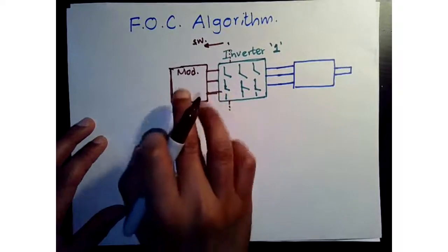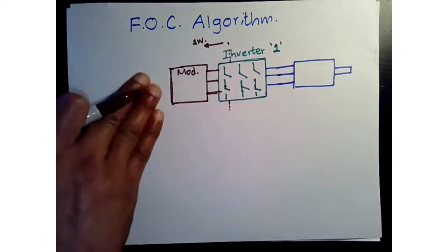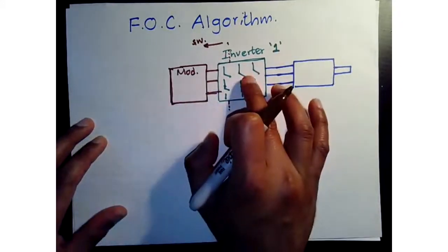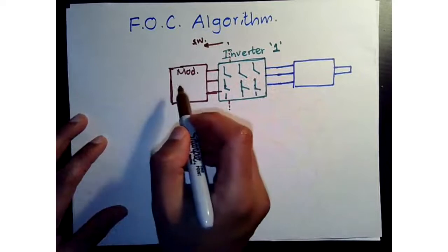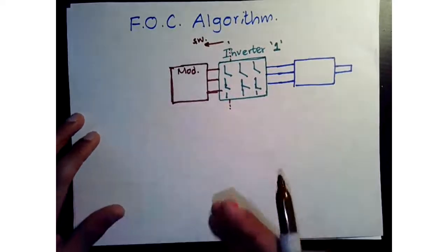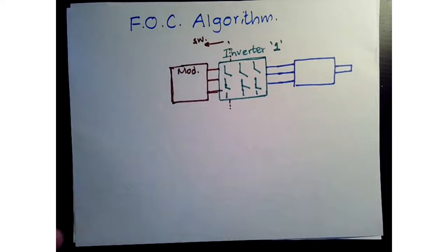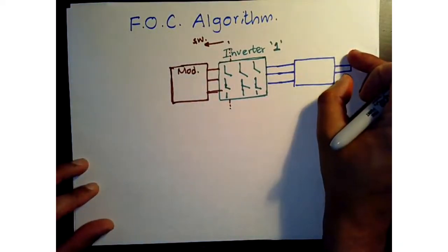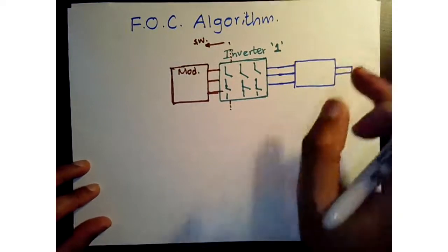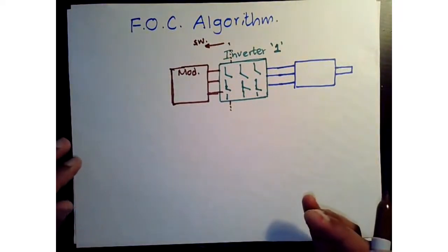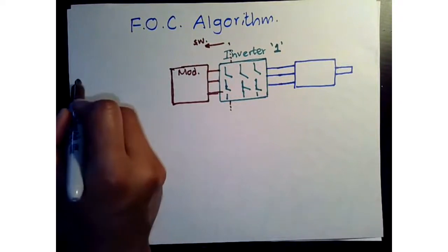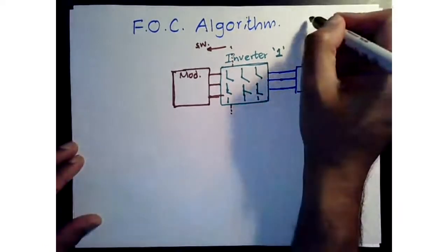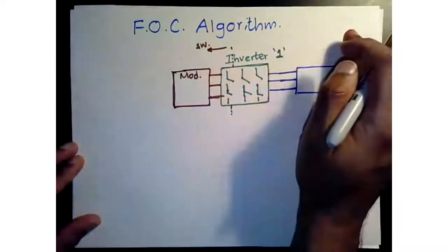go along, because for us to apply voltage, we need to say, okay, how much voltage to apply. That voltage needs to be converted to a PWM signal. All right, now how much voltage needs to be applied needs to be based on where we want to go, right? How much torque do we need to apply? All right, that comes from a torque command. I don't want to draw that there because I might run out of room here.